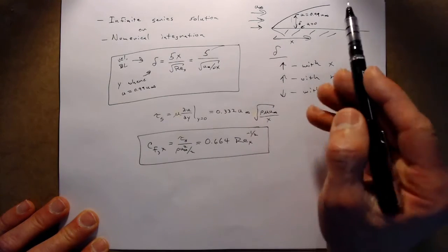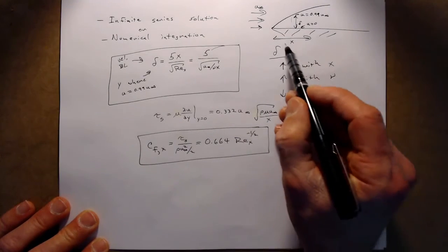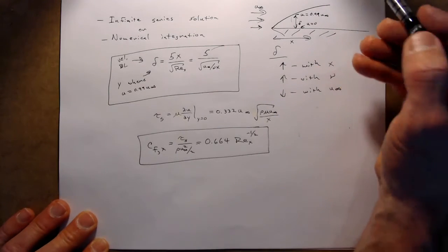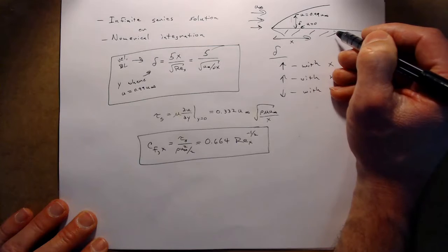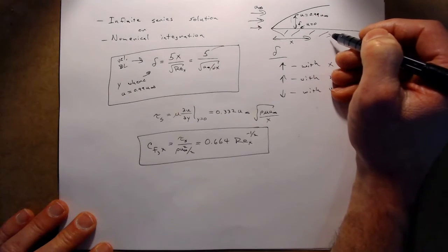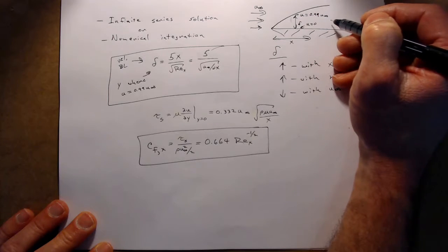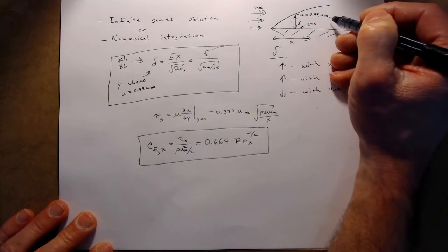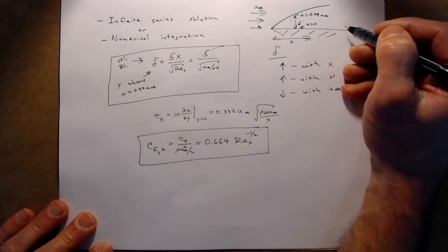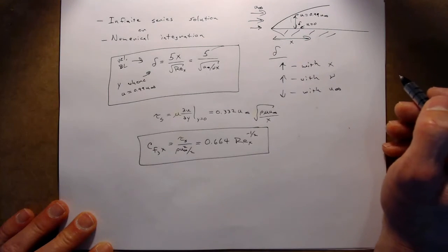So from that we can quickly see some implications about the boundary layer. One is, as we move further along the plate, the boundary layer grows with x. This is what we expect. The momentum is being sucked out of the flow, the surface is imposing drag on the flow, and that's going to slow the flow down in a layer that keeps propagating deeper and deeper into the flow as we go further along the plate.